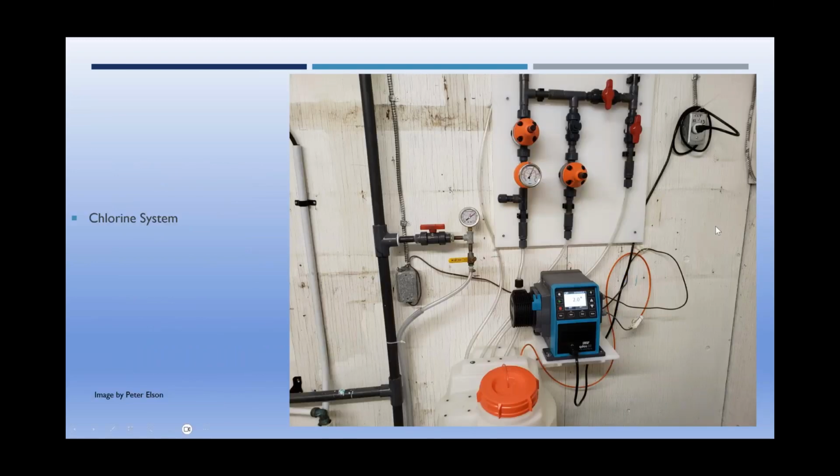So this is a fairly typical one pump chlorine system. Most chlorine systems will have 2 pumps these days. Sometimes they run alternately, and sometimes one is just sitting aside as a reserve, which is what I tend to prefer. If you've got 2 pumps running alternately, you can run into a few problems. The obvious one is that although they'll last longer, they'll both fail about the same time. But also, if one pump is faulty, it can be very difficult to determine what's happening.